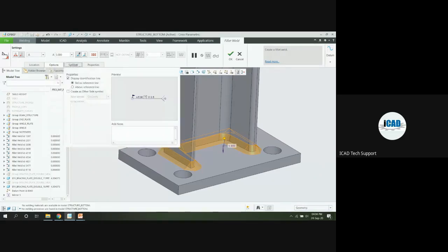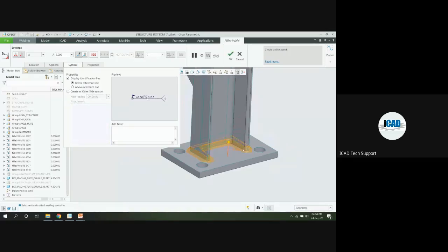And in the symbol gallery, now we can see the type and the size of welding we have added here as a 5. After this, 5 automatically gets added. The finish type of symbol we want to add here, so the finish symbol is added. And then the convex shape symbol also gets generated. So this type of standard welding symbols automatically gets generated. You can create them, and if we want separate symbols on the other side also, this way we can add them.